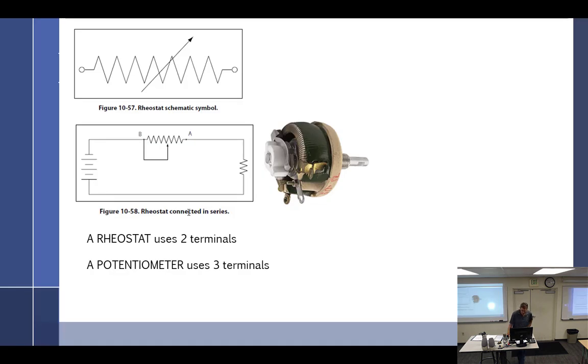There we go. A rheostat is simply a variable resistor, variable resistance used to control power to a load. The correct term for the common terminal of the potentiometer is a slider. Only the slider and one other terminal are used. Potentiometer uses all 3 terminals, enabling a variable voltage or signal to be tapped off from the slider.